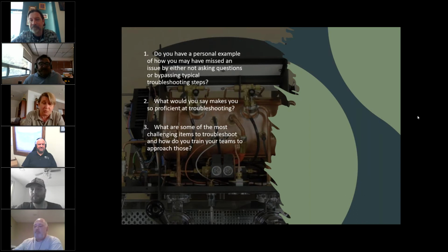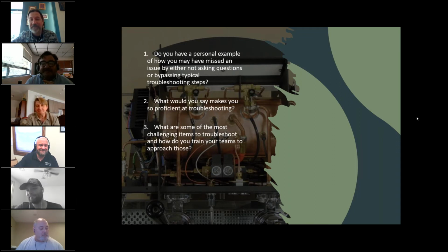If you see a wire is all crispy, that might give you an indication of where to start with the troubleshooting process. Also check ground. I've had so many steam boilers overheat where there was a loose wire in the cord cap for ground. So there's your boilerplate answer. I'm sure there's a ton of other things in that space around how an overpressure valve might pop off, but that kind of hits it.